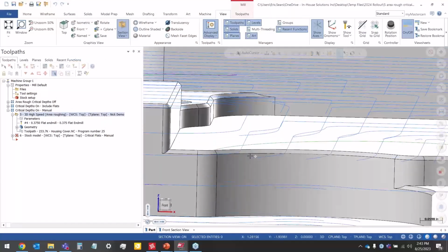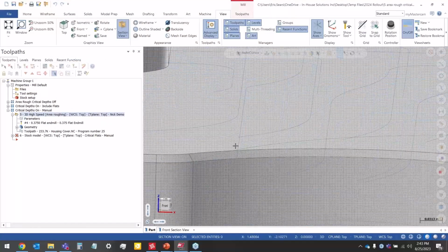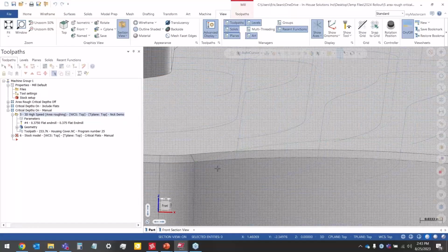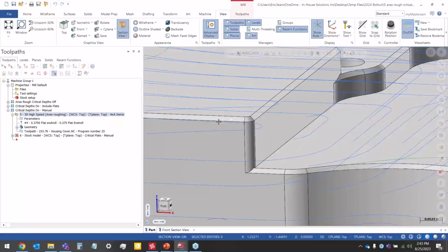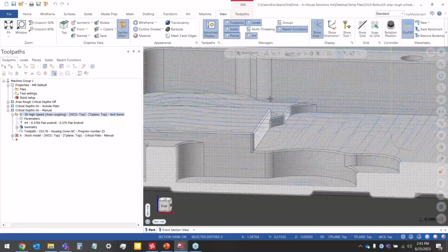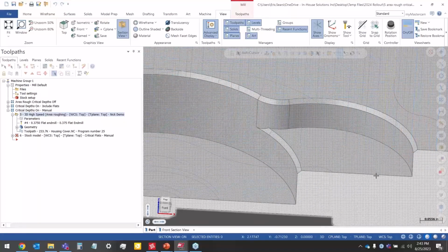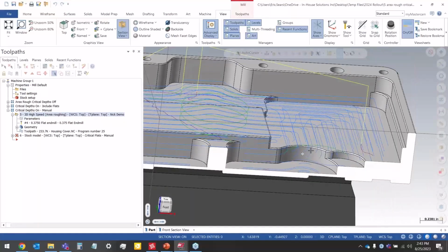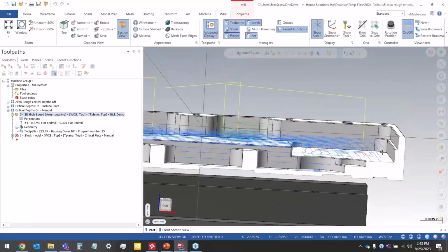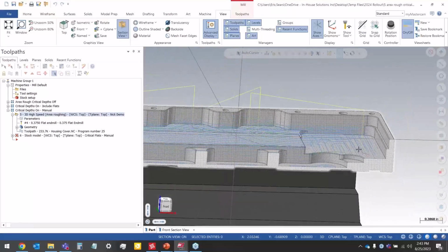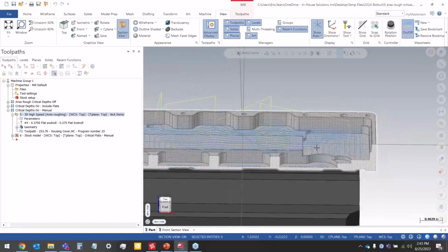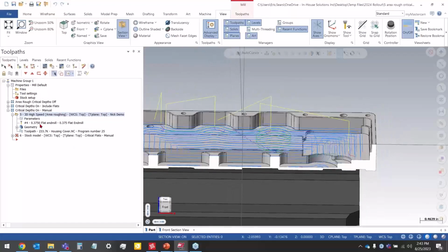And you can see that now I'm machining that floor right to 0 as I programmed. And all the flats are getting hit. You can see the pocket down there, this little open pocket, they're all getting hit. So it's a small feature, but I think it's a nice thing to have. But that's it for the area roughing toolpath.